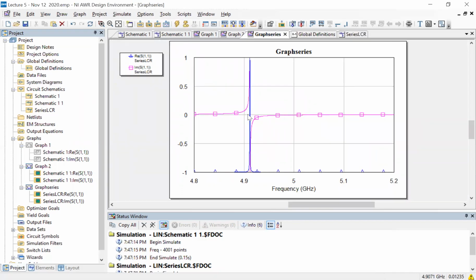Now it's the inductor adding to the inductor as opposed to the capacitor adding to the capacitor. So it's a very nicely dual thing. Capacitors become inductors, and inductors become capacitors. So now you can see the shape is again very similar. It's just there's an overall phase shift again because of the same kind of situation. So the real part is going from -1 to +1. The imaginary part goes in the other direction, but it's perfectly fine. Okay, great. Yeah, that was a good question to ask.